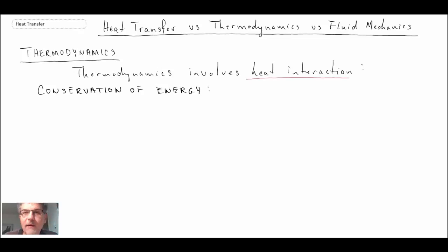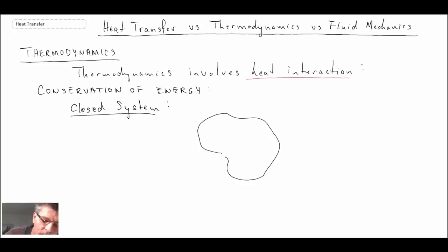And you could have either a closed system or an open system. And depending upon the system that you're using, the conservation of energy or the first law of thermodynamics will look a little different. So let's take a look at a closed system to begin with. When we're dealing with closed systems in thermodynamics, quite often what we will show is interaction between the system and the surroundings, and interactions can be in the form of heat transfer, Q.